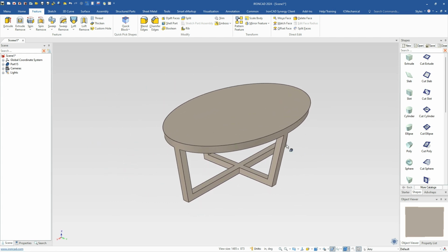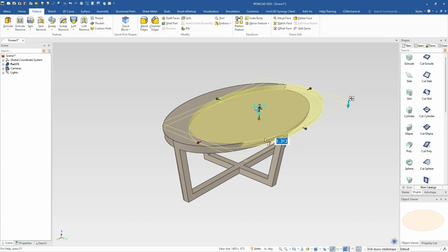So next, we need to have this other shape inside of here as well. So again, you can use a sketch if you like to offset that. You could use another cut shape inside of here. So again, we'll just drop another elliptical shape out here. And again, we don't really have a center point to go off of, but we do know the side of this thing is 45, and we know it's 27 on the other angle, so 27 that way. And we're just going to set the depth of that to be 0.5 for now.